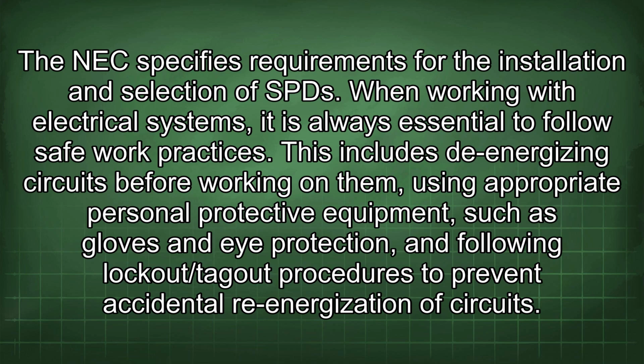When working with electrical systems, it is always essential to follow safe work practices. This includes de-energizing circuits before working on them, using appropriate personal protective equipment, such as gloves and eye protection, and following lockout/tagout procedures to prevent accidental re-energization of circuits.